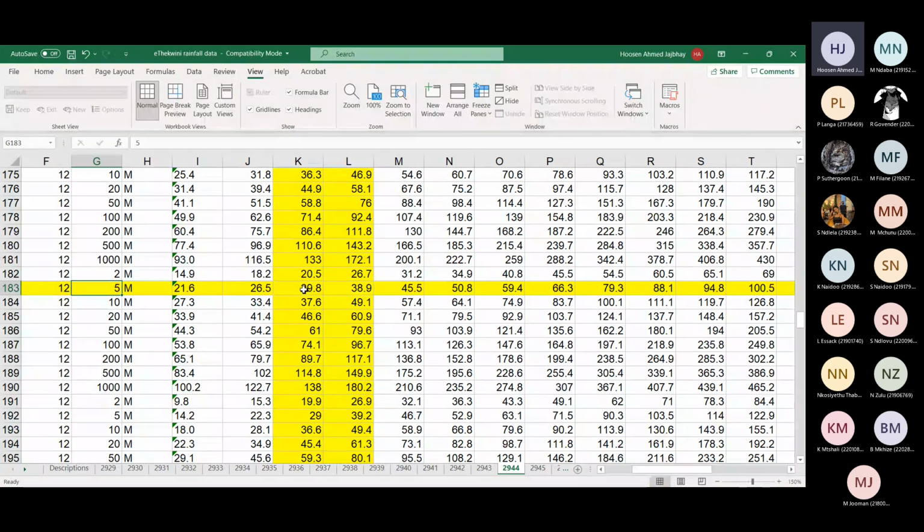So this is where you come and you look up the site-specific data that eThekwini has provided for you. So they have the spreadsheet. It covers the entire eThekwini region. And for any point in eThekwini, you can get the rainfall data, the point rainfall data. And this is based on historical records. Right? They have historical records, and it's been derived from the historical records. They do have points in the city where they measure the rainfall, various areas and various points, and it's derived from that. So this is from historical data. And so interpolate between those two values.